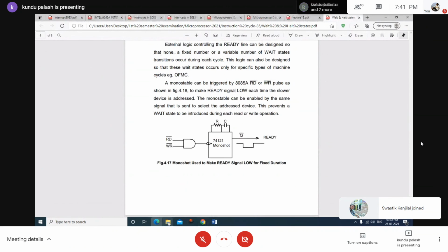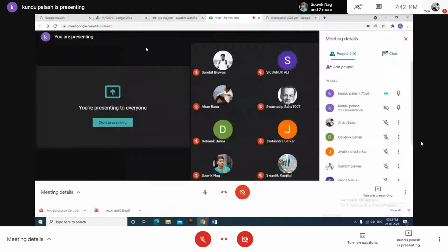What is the bus cycle? Upon execution of the halt instruction, the microprocessor will stop fetching opcodes and doing anything, but rather all the signals, as well as the timing and control and the address and data bus, will go into the high impedance state, called bus idle machine cycles. So that is the significance of the bus idle machine cycle.